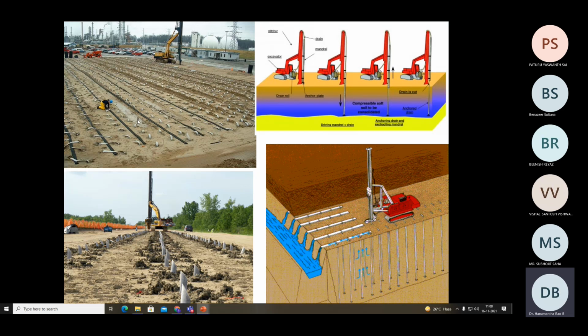But of course this is right at the installation time, but with time you can notice the movement of the water coming from the down to the upward direction. And the moment you provide the drainage blanket, it makes an interconnection of all the PVDs, as we can see in the right side bottom diagram. So the water which is seeping in the upward direction from the bottom will be collected in the blanket, and from there it is diverted to some collection tank.